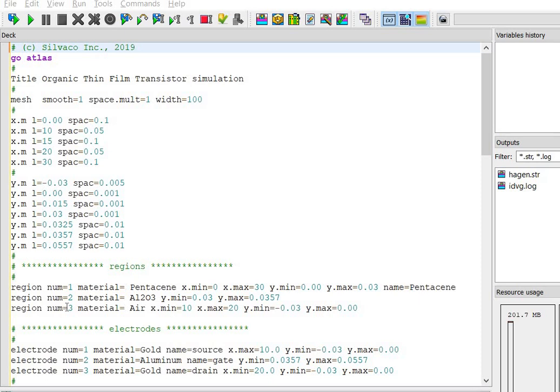Next is the electrode material. At the top of the organic material, at the drain side and the source side, we are using the gold material, and electrode name 2 contains aluminum material at the channel region. The gate material comprised of aluminum material with their positional parameter.